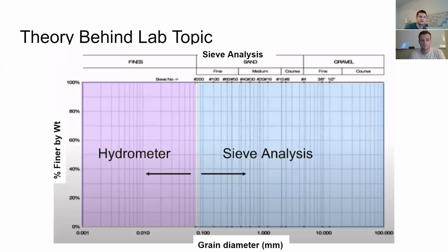Grain size distribution is a major component of soil classification using the Unified Soil Classification System, USCS. The standard grain size analysis test determines the relative proportion of different grain sizes as they are distributed among certain size ranges. Larger particle testing is accomplished using sieves. Sieve analysis allows you to directly measure the mass retained and mass passing a specific diameter particle size. These values can be used to calculate percent retained and percent finer in order to construct a grain size distribution